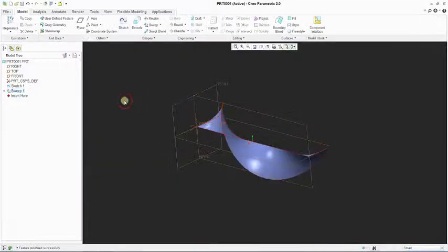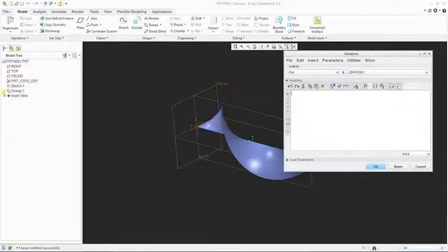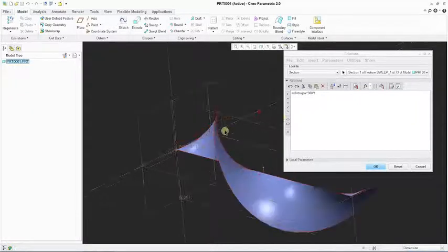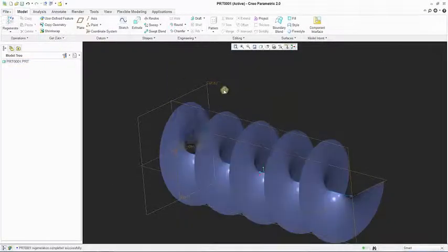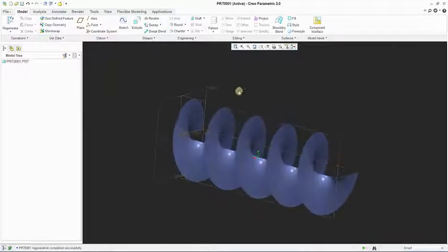Now we can increase the number of turns, or we can reduce it to 180 degrees. So let's go ahead and change the number of turns. We'll take relations, expand this, and select section in this place. It's a little bit of a lengthy process. You can see the line has changed to a horizontal position and I've said 1 here. Let me make it, let's say, 5. I say okay and regenerate the model, and you can see you have created a 5 turn using a simple equation. Trajpar does this. It's basically two variables which are varying simultaneously. That is what is happening in this place.